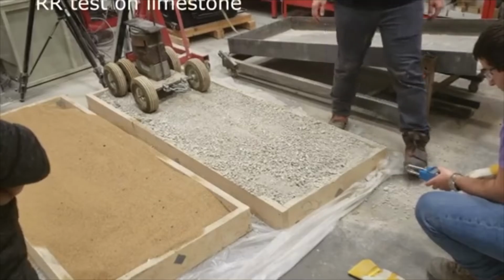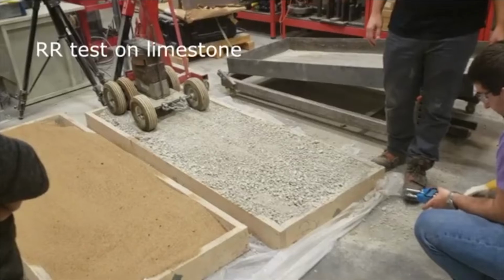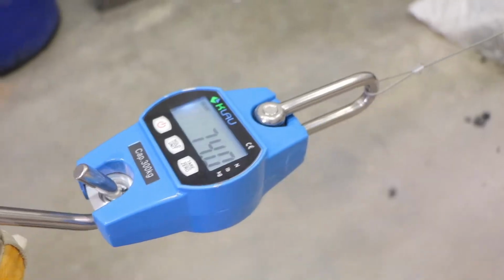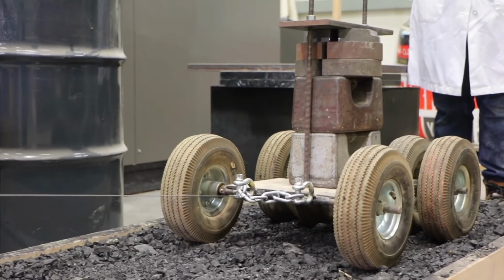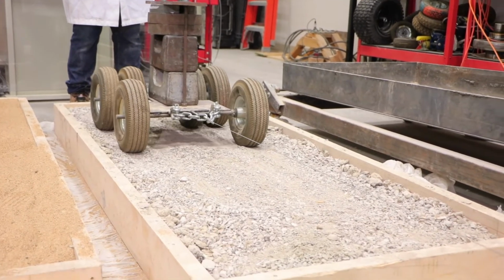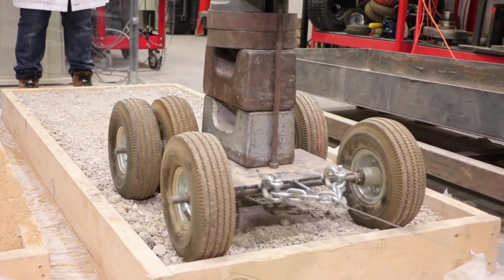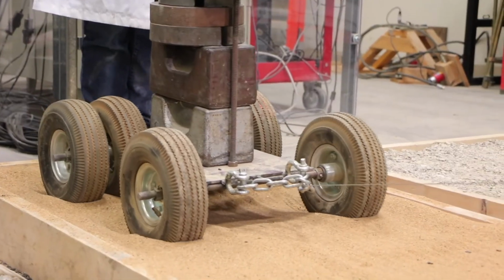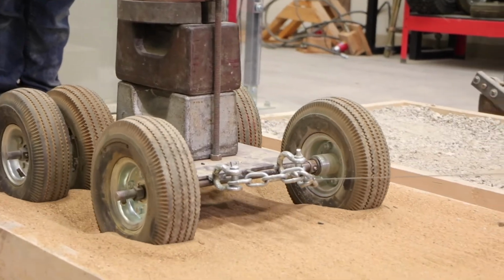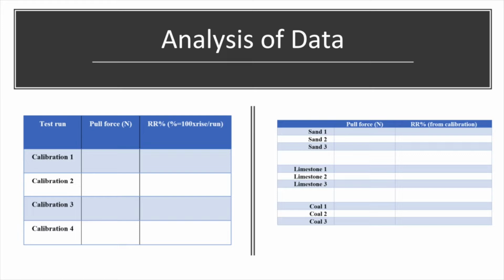For the test itself, we have 3 different materials we will be comparing: coal, sand, and limestone. First, we ensure the test beds are level, then set the vehicle at the end of the test bed, pull it steadily across the bed as we did in the calibration portion of the test, and repeat this process for each of our test materials at least 3 times to observe how compaction impacts rolling resistance. Now it is time for you to analyze the data.